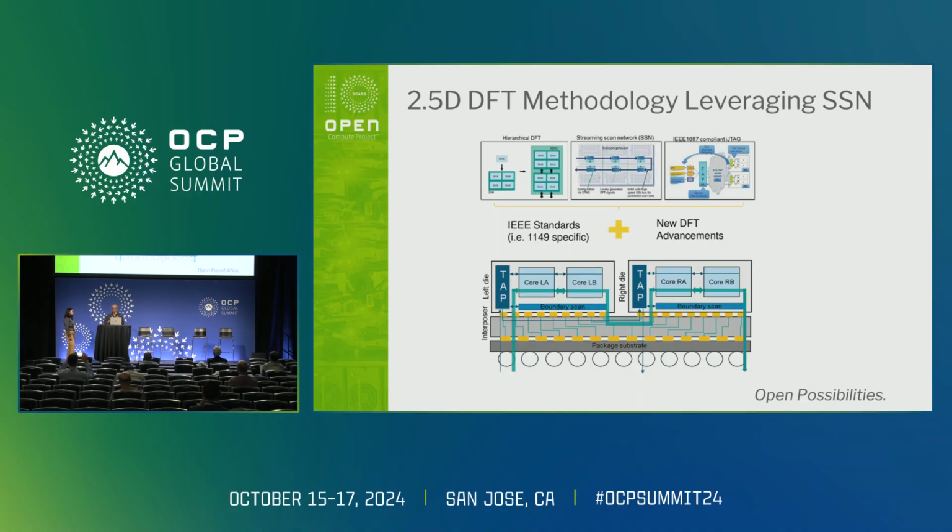short or open, and with this existing standard, with both chips having the same standard implemented, you can check the interconnection test between the left die and the right die. And the upper picture is showing the current state of the art, which the test companies are adding, how to basically packetize the test data to increase the test speed with these mechanisms.